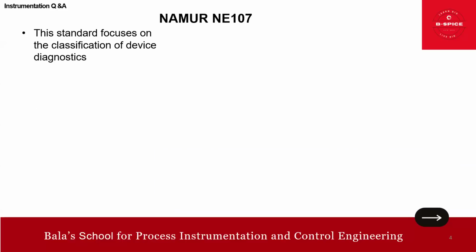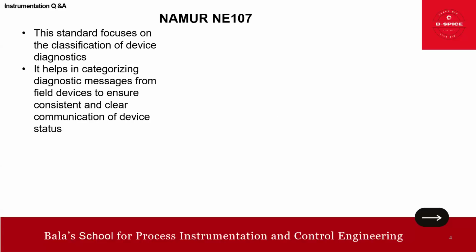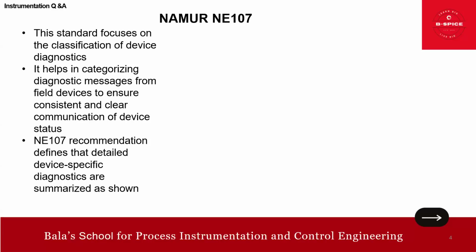Now, this classification, what is this? This focuses on the classification of device diagnostics. Basically, this is NE107. Like NE43, we also have NE107. NE107 focuses on the classification of device diagnostics. It helps in categorizing diagnostic messages from field devices to ensure consistent and clear communication of device status.